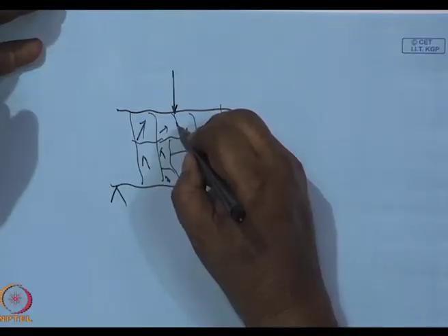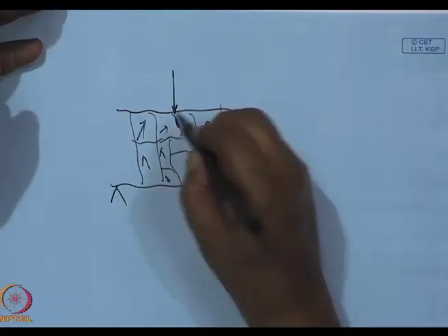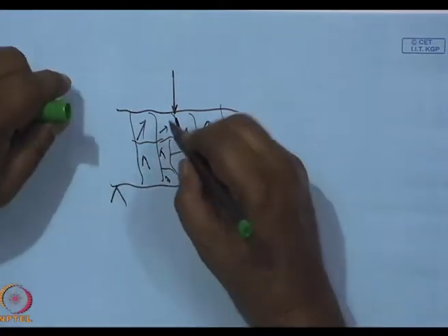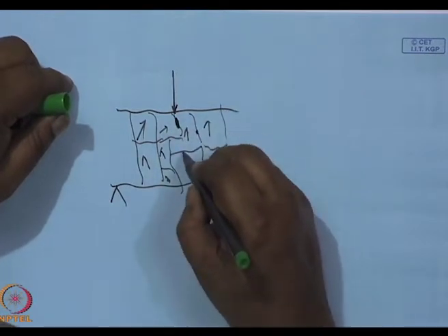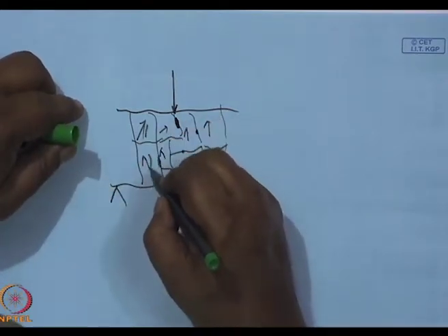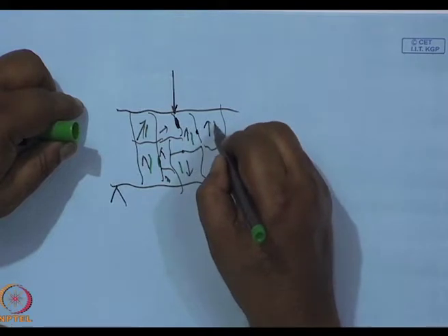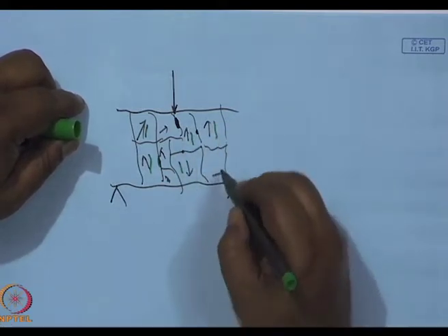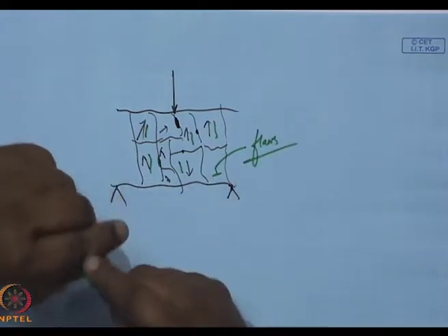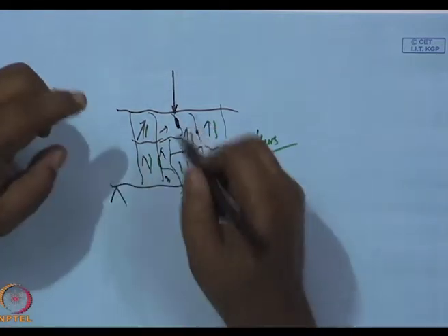However, in this microstructure, there are many flaws. There might be flaws in the grain boundaries. Over here, there might be flaws within the grains. All of these are flaws. Now, as I keep on increasing this load, nothing initially happens. The energy simply gets stored within the matrix.